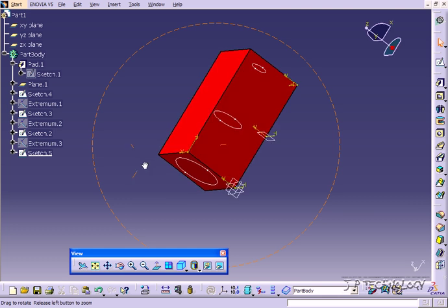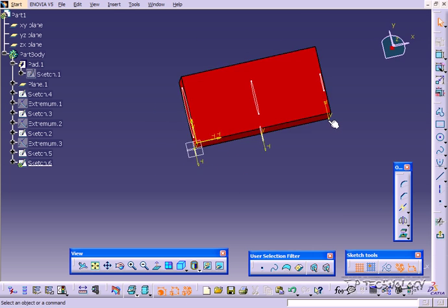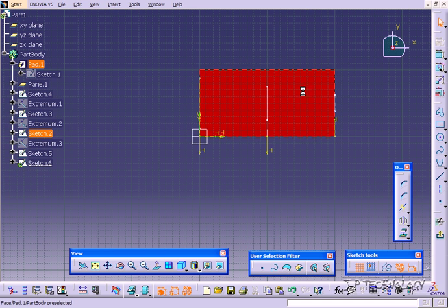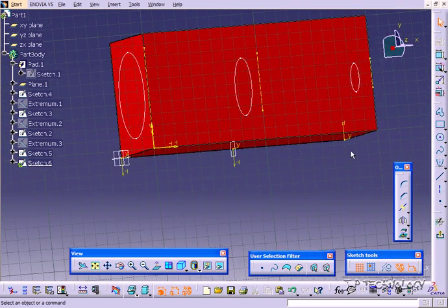So what we're going to do is connect them all by making a sketch at the top, like a spline, so a path that it can follow. So let's click the top face, click sketch, and let's click each of these circles, and we'll project them out, make them construction lines, and if you put it on the side you can see that they're all construction lines, and we're going to use them in the construction of our spline.